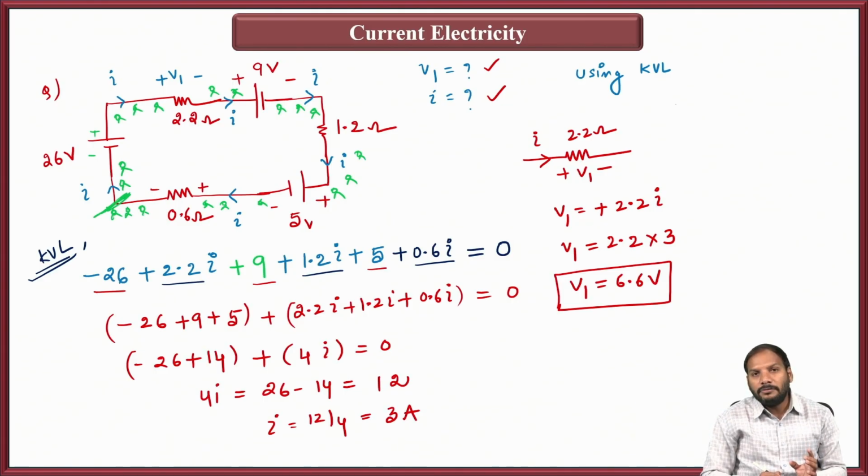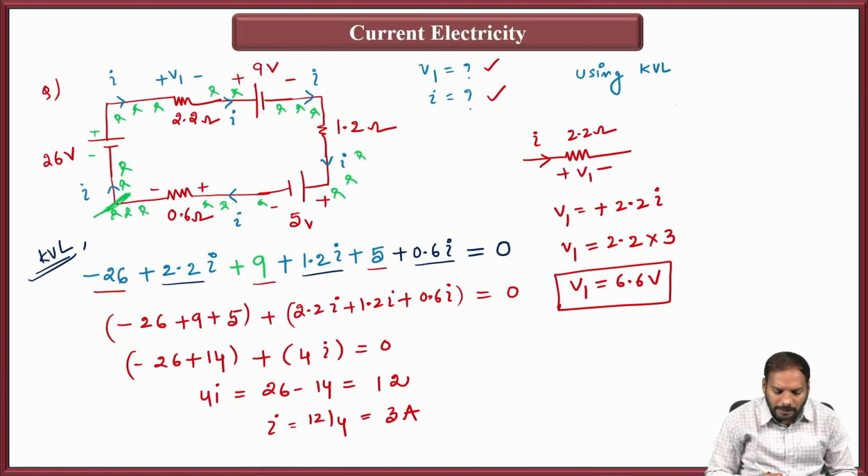So the important observation you need to make is, whenever you are walking, if the current in the element is exactly with you, then take it as positive convention. If the current is coming opposite to you, take it as negative convention. So try to solve all the problems using the same approach. Certainly, you will get excellent and accurate results in the solution analysis.